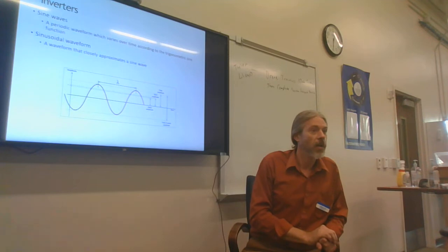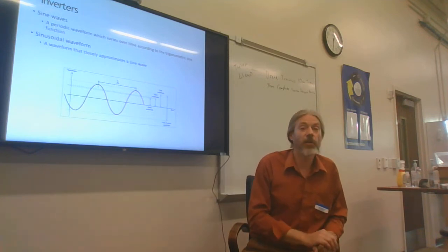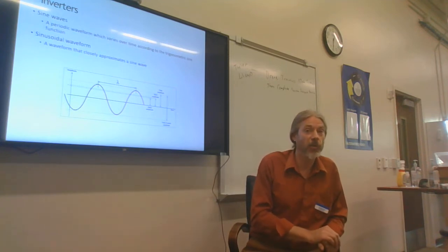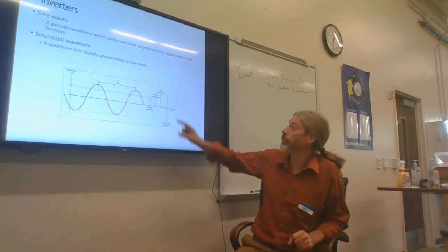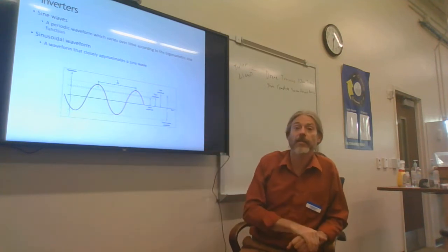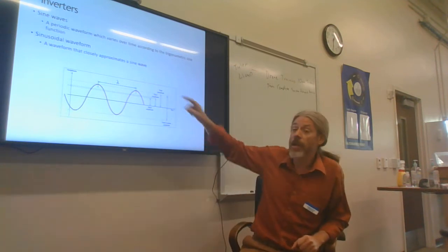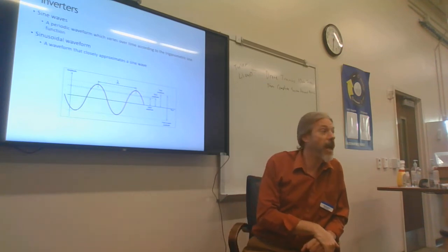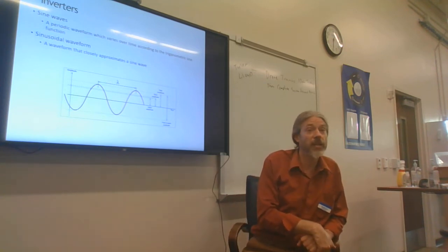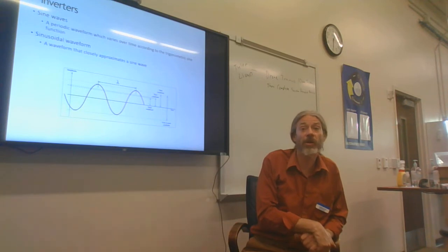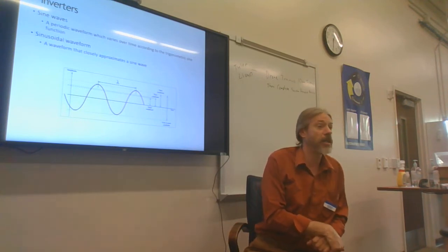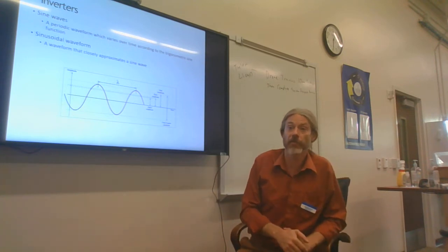Typically you think, oh, they're only handling 240 volts. That 240 volts is the RMS. The peak is going to be noticeably higher than that. And so that's part of the reason that the wires in the wall aren't only rated to handle 250 volts. They're rated to handle all the way up to 600 volts.